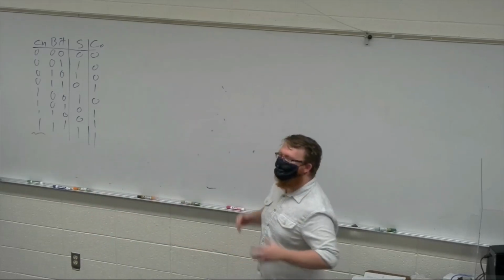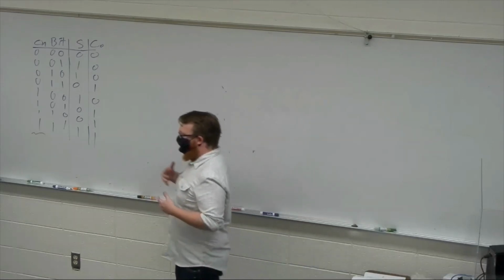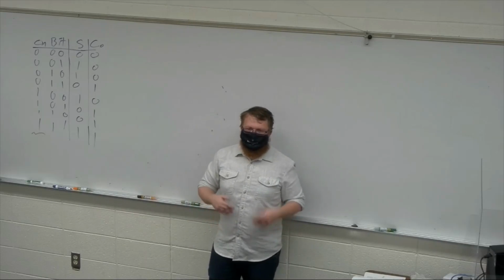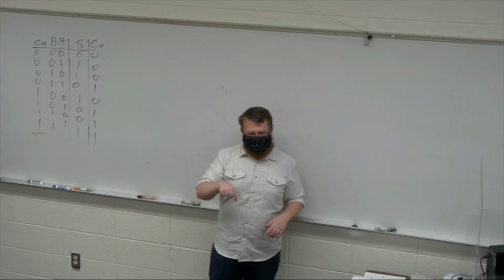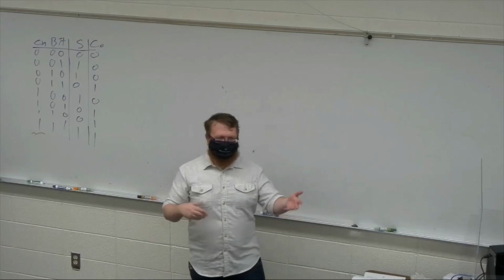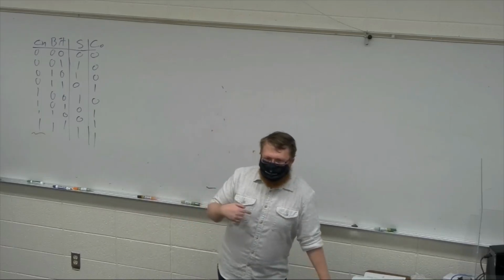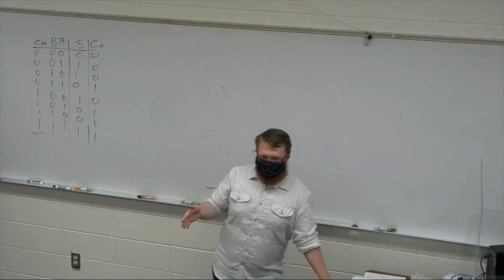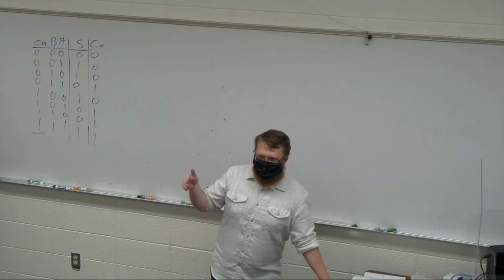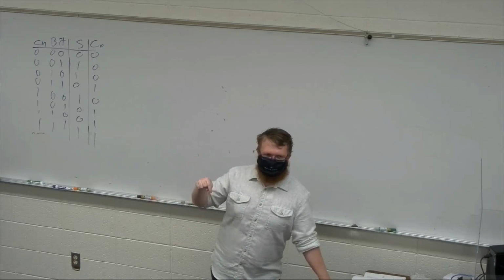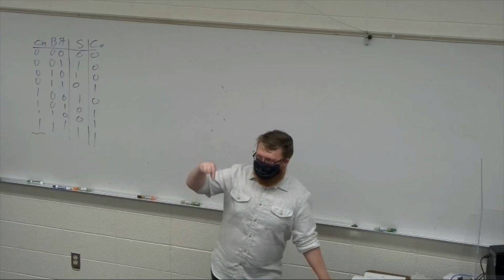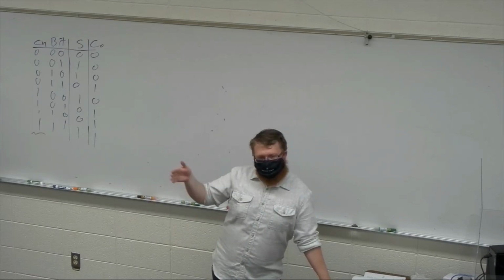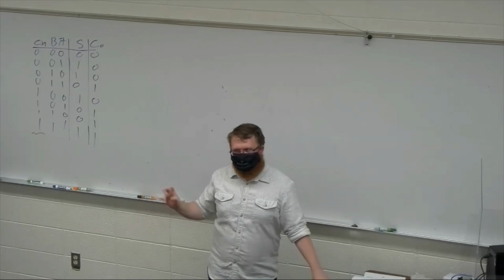So debouncing is a solution to a problem that we get in the real world. If you and I push a button, and our FPGA is running at 100 megahertz, compared to us, that clock is very fast. So if I have a counter that's trying to count the number of button pushes I do, and I just touch it and let go as fast as I can, there's two different problems we could run into. Both of these are kind of debouncing problems.